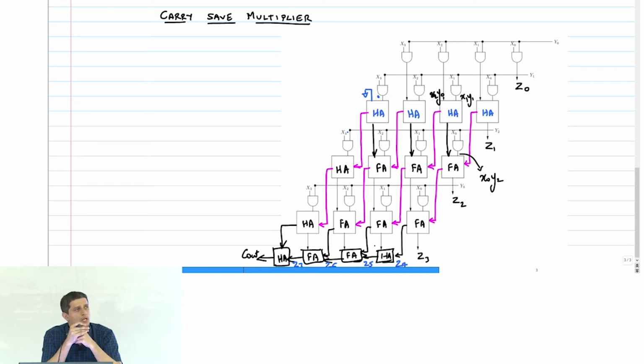How am I sure that C out will not matter? No, you're right. I know. So, yeah, what he's saying is effectively, I think what they're saying is right. C out will always be 0, because if you propagate this X3, Y1 down and remove that half adder, you can basically remove this set of half adders.